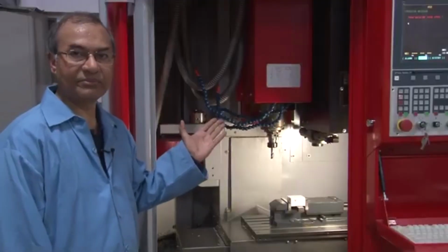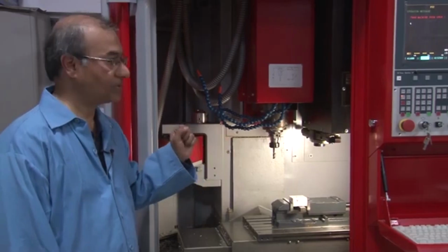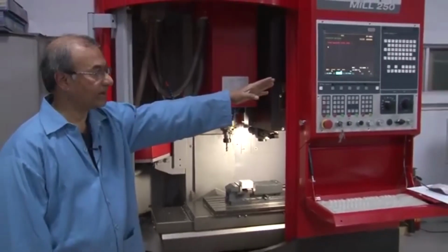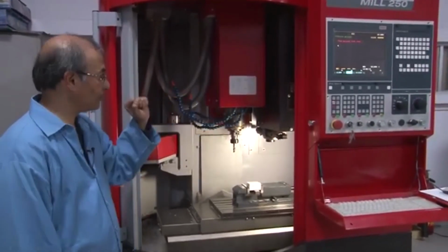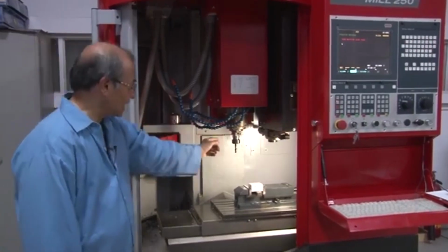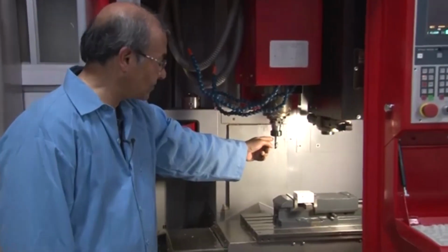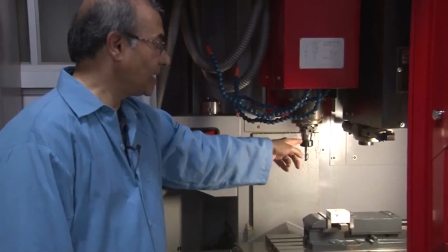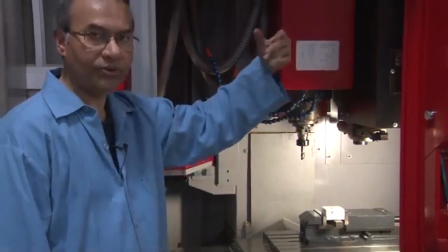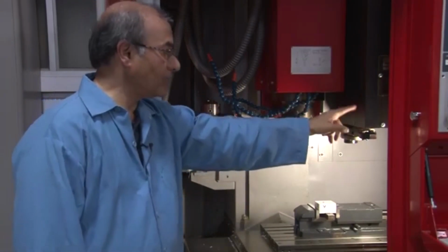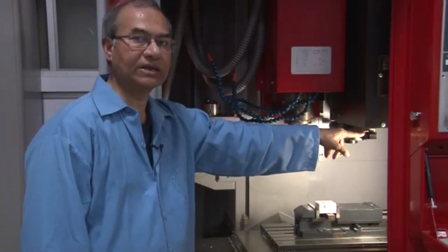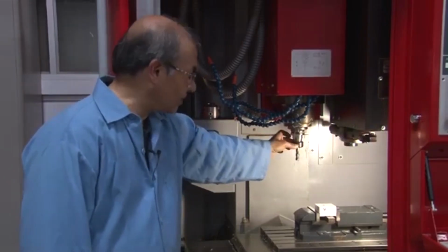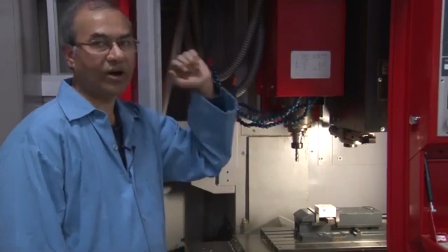Okay. Here you can see this is the milling machine, CNC milling machine. Here the control panel is absolutely the same as in the case of the turning that we have demonstrated to you. In the machine you can see that this is the spindle in which the tool is mounted. Now, in this case the tool has to be taken from the turret head, which we are going to show you, and the tool will be taken by the automatic tool changer. There is an automatic tool changer which will remove this tool, and the required tool will be coming from the turret head according to the program.